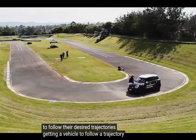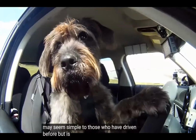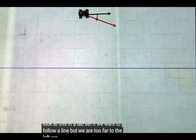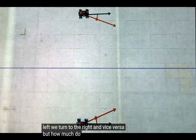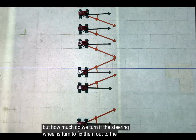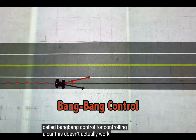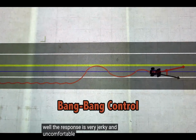Getting a vehicle to follow a trajectory may seem simple to those who have driven before, but is it? Let's take a deeper look at this in a lab setting. If we want to follow a line, but we are too far to the left, we turn to the right, and vice versa. But how much do we turn? If the steering wheel is turned a fixed amount to the left or to the right, the approach is called bang-bang control. For controlling a car, this doesn't actually work that well. The response is very jerky and uncomfortable for the passengers.